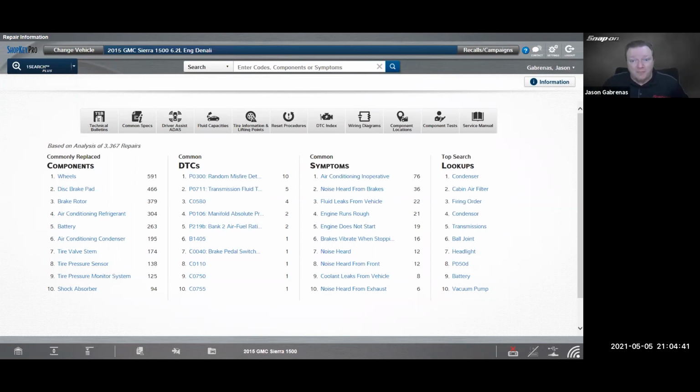I actually had a BMW with that kind of problem. It was an older one. It had the round connector under the hood still, but it had the OBD2 under the dash. It had no communication with the ECM. Traced it back to a connector where they were all spliced together under the footwell, and the car had gotten flooded, so it was all green and crusty. So that was the problem right there. It's a one-off situation. So definitely, that'll cause a bus problem. Usually it's a module, some sort of internal power of the module.